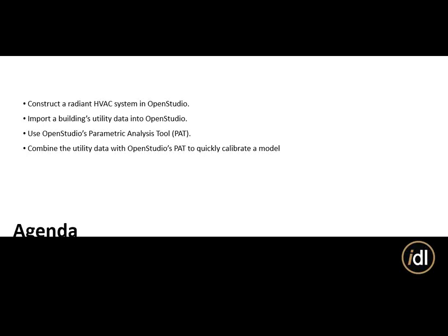And then they're developing some new calibration tools within it, and so we'll talk a little bit about that. I'll give a demonstration on that as well, where you can actually import your building's utility data and get a very quick visual to see how your model is performing in comparison to that. And lastly, I want to link that with what's recently launched from them, their Parametric Analysis tool, where you can run hundreds of simulations very, very quickly, change lots of different variables, and then see how that affects your calibration.